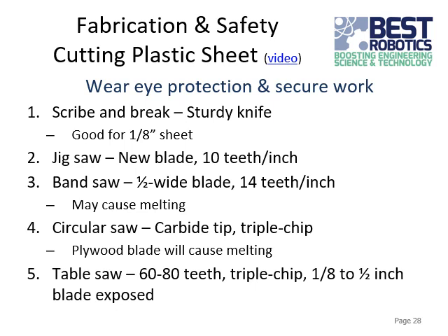Just go slow with it. This is the recommended teeth per inch: 10 teeth per inch, but you can see the blades will sometimes say if they're good for cutting plastic or something like that. Again, you want to make sure that your workpiece is really well supported in that case. Otherwise, the jigsaw may break pieces off.